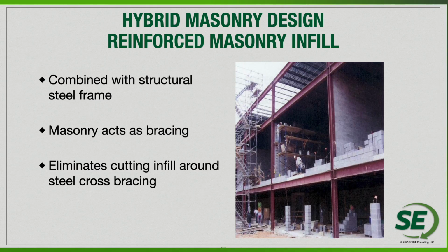Looking at hybrid designs, it's simply going to be a frame that's going to be built, and a lot of times it's going to be a constructor-led decision where the contractor wants to go with the all-steel erection, so steel columns and beams and floor members all at once, and then the sequence of adding in masonry would be after the fact. So again, if that's the overall construction sequence, certainly a hybrid design can work pretty well because maybe the masonry is there for multiple reasons, architecturally and structurally.